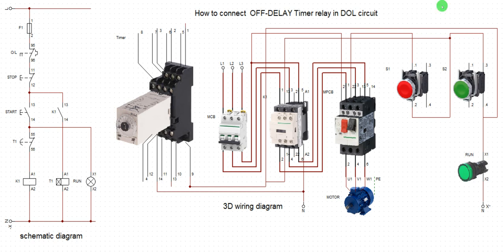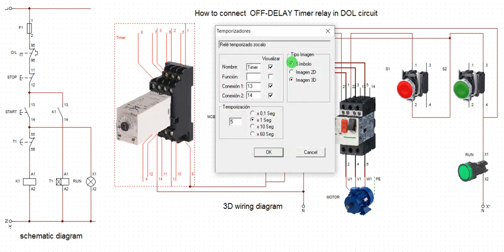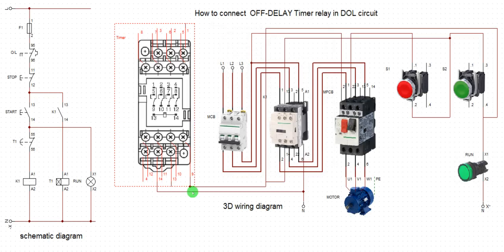Okay, all right. Now pay attention, please. Now let me take you back to the symbol. Okay, take a look at the symbol so that you see the contact arrangement. Now check 13 and 14 are the input to the coil. 14 is the A2, that is neutral. Then 13 is the A1, that is a live conductor terminal, that is supplied to the relay. Okay, so I'm using 13, 14 to energize the relay. Then I'm using 9 and 1, this circuit, to feed my circuit.